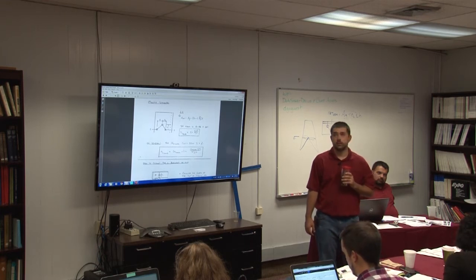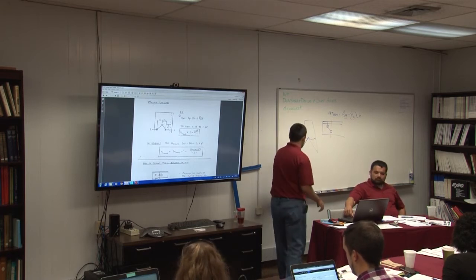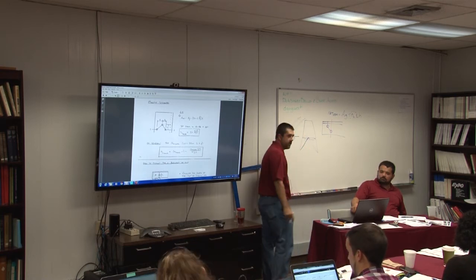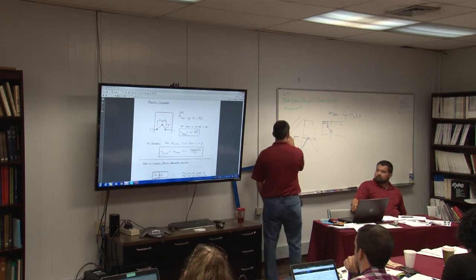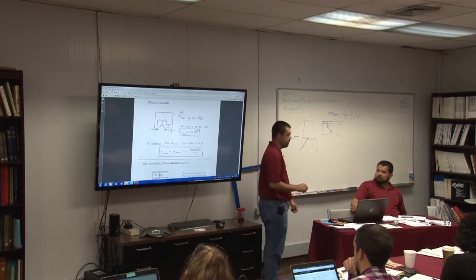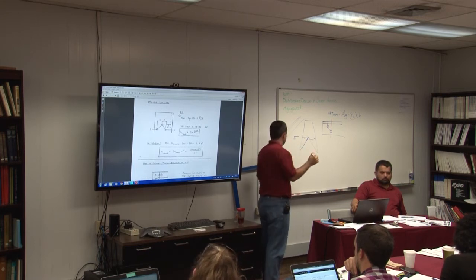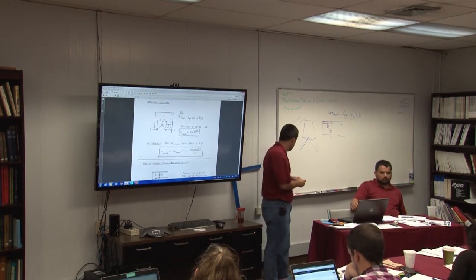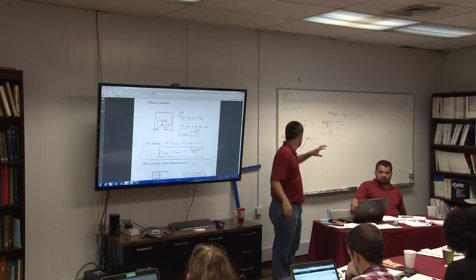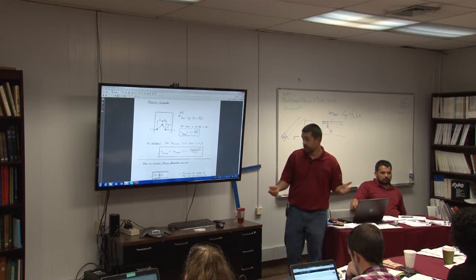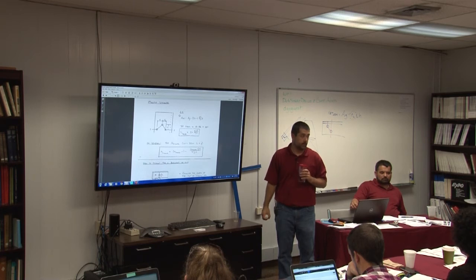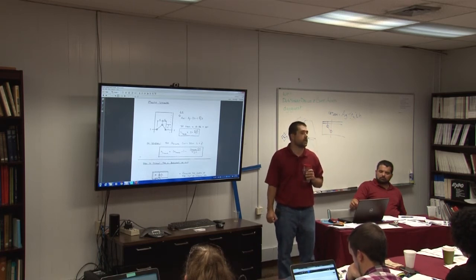Now, again, if you have a diagonal member that has hole patterns like that, this is an easy calculation. It's 1, right? A lot of times these things might be off slightly, but it's only to fit the bolts in. But you can look at this and see that the stagger is so dramatic that it's 1, right? So really, a lot of times it's leg modeling, or as you get higher in voltages and you get more bolts in a connection, the more of a nightmare this becomes. So the higher voltage towers become more difficult to do. But we look at it for every member, and there are definitely diagonals that overstress in that section.